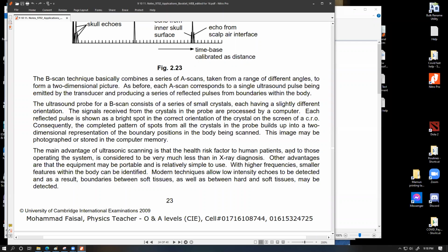To make a complete scan or a perfectly understandable scan, what do we have to do? We have to first use the crystal to produce a pulse, then stop the sending pulse and wait for the reflections to come by, and allow the whole reflections to come and detect all of the voltages individually. And then once the process is done, we should energize this a second time. So the gap between consecutive send pulses will be something.